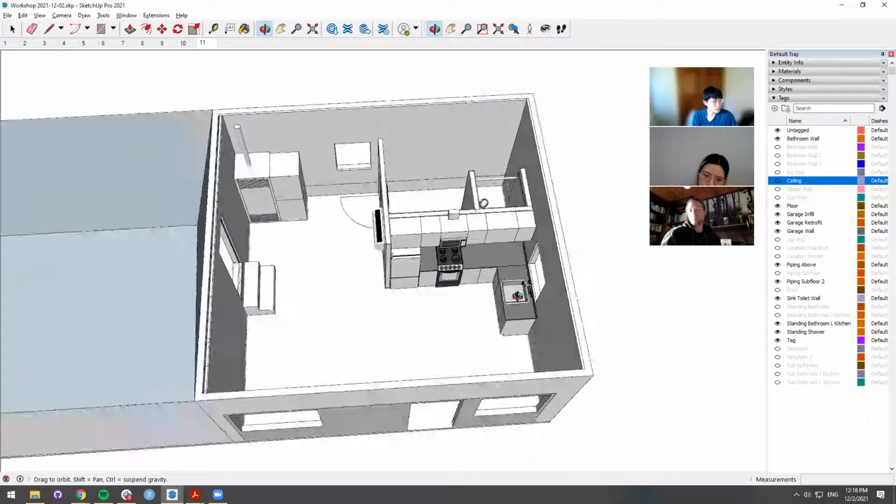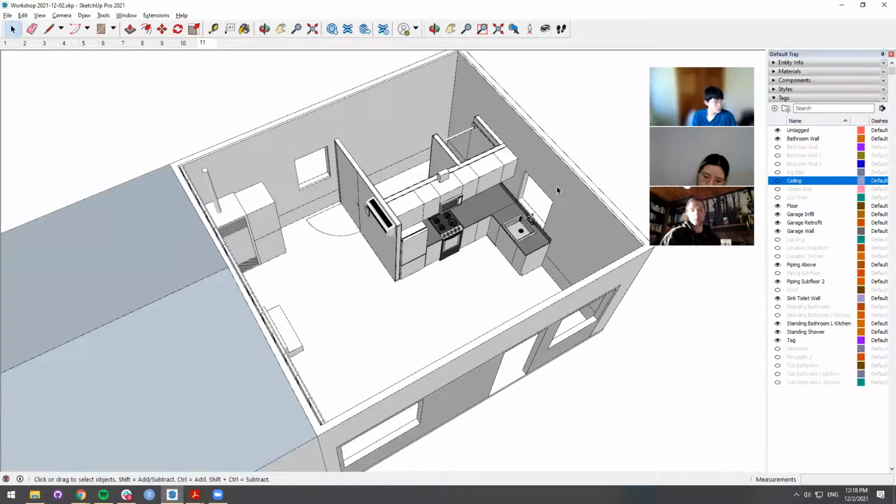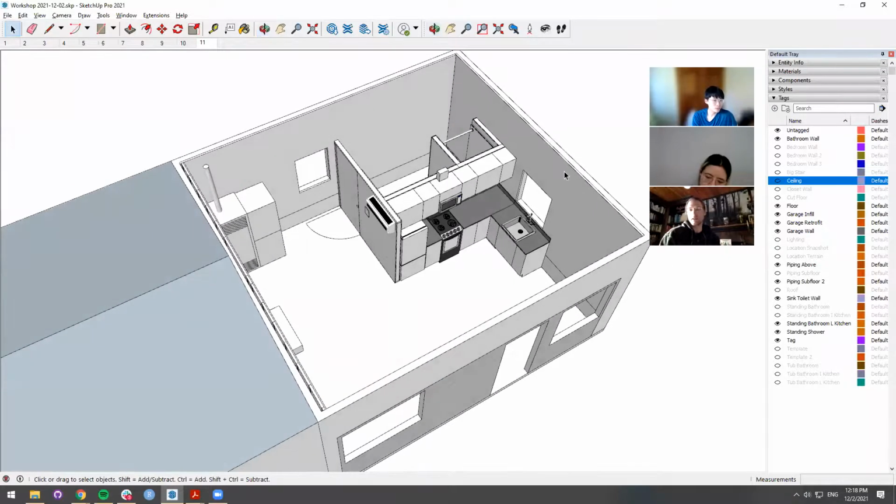Ventilation, aside from exhaust: you need supply air, especially if you've got a gas burning water heater that needs venting. Yes, this is probably not the most airtight assembly to start with, but I don't know if through Title 24 you'll have to adjust or even provide makeup air. And in my mind, that front facade that fills in the garage would be the appropriate place for a pre-added, pre-wired ventilation solution.